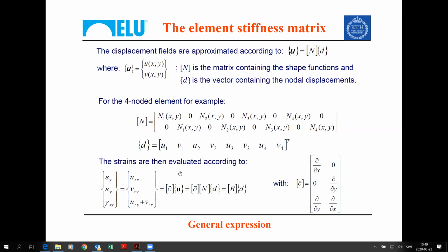The strains are evaluated by applying the differential operator, delta, on the vector of displacements u. So epsilon is du dx, dv dy, du dy plus dv dx.